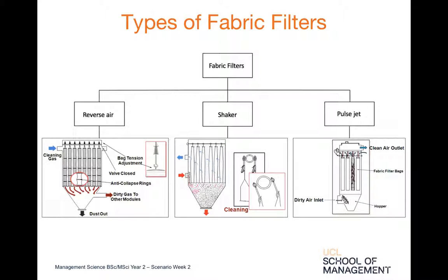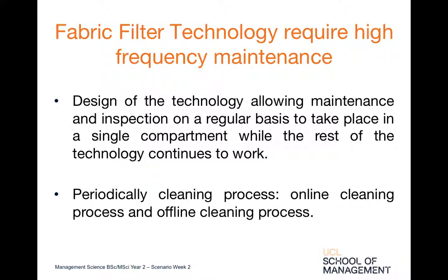in a reverse direction. For the shaker, motors shake the top horizontal bar from which the bags are suspended. During the pulse jet process, bags are cleaned by a short burst of compressed air injected through a common manifold over a row of bags. Fabric filter technology uses a fabric filter media to collect the particulate in a flue gas. Such fabric filter media takes the form of long and cylindrical bags. Thousands of these bags are gathered in the pulse valve.